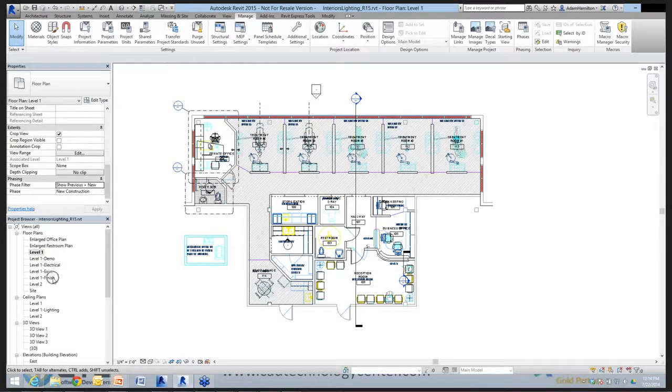I created a finished plan and renamed it, and the electrical plan and renamed it. Renaming views is also very important, as you can see, sorting, and we don't like unnamed views or default name views, because a lot of times you lose what it is you're looking for. And believe me, when I've worked in projects inside Revit, at the end of 1 week we could have over 100 3D views. And so good naming standards is always important.